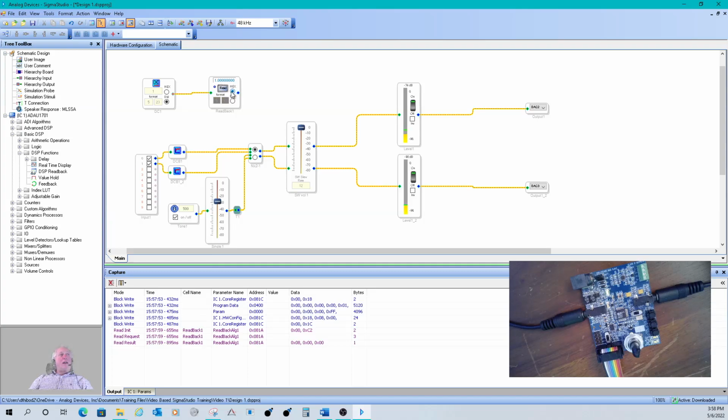So if you go to hex and you do the read as a hex, you're going to see the top 24 bits. You won't see the bottom bits. So you have to do a couple of multiplies. We'll show that in another project. But what's handy about this thing to keep in your project is it will show you that you are communicating with your DSP properly.